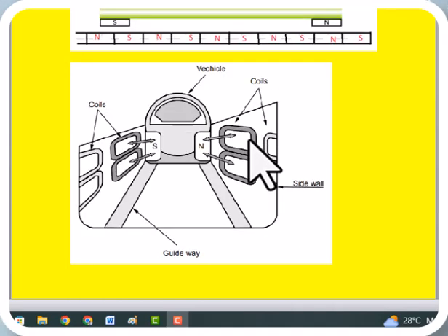Whereas the coils which are vertically placed on the guideway are responsible for movement of the train forward, because on the guideway you find the north pole here, whereas on the train sideways we find the south pole, and similarly here north pole, and here is also south pole on the train sides. The south pole will be attracted towards the north pole, so the train will move towards this, from right to left, and once it comes here, again you have the south pole here, it will reject this. Similarly here there is a north pole, this north pole will be attracted toward the south pole, so it moves forward, that is, ultimately it makes the train move forward.